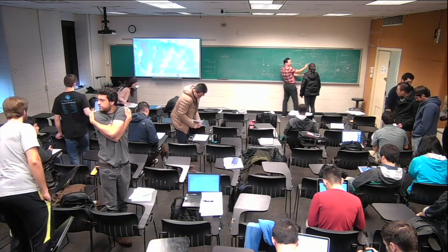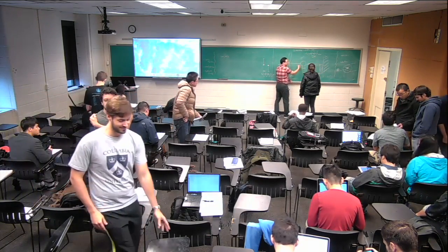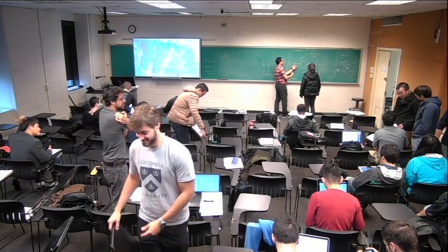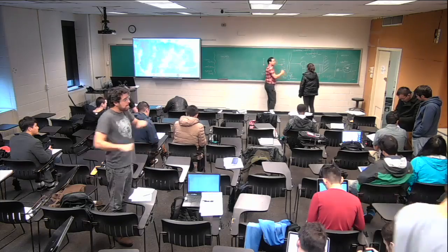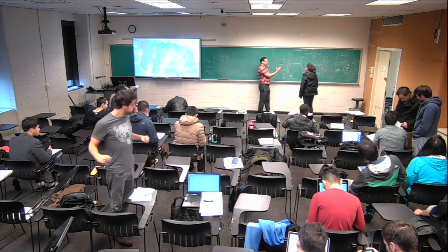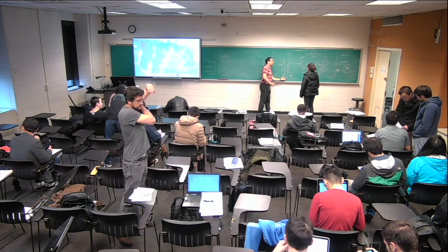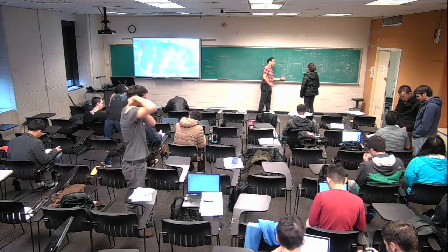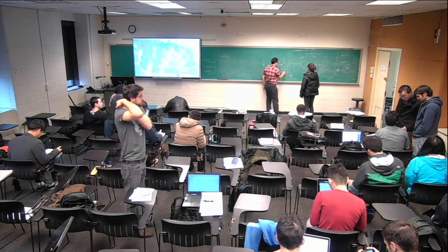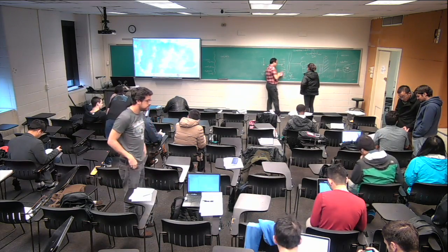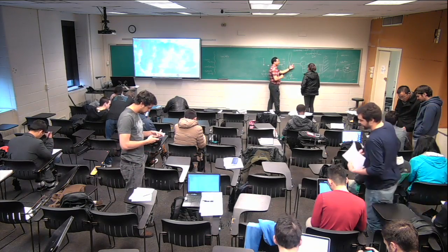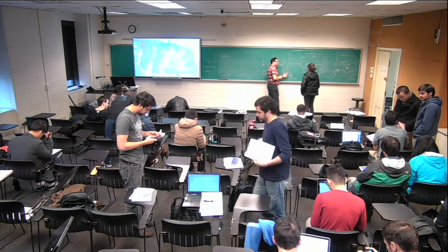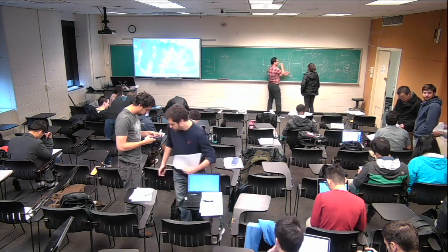Right. But if there is a feedback, then you can have torque control to make sure that this rotation comes out of wind here. First you would say, I want to maximize my efficiency. Efficiency is a number, a constant, for example 0.4. Then this ratio should be constant no matter what the wind is. The rotation here should be 4 times smaller than the wind that you see here.